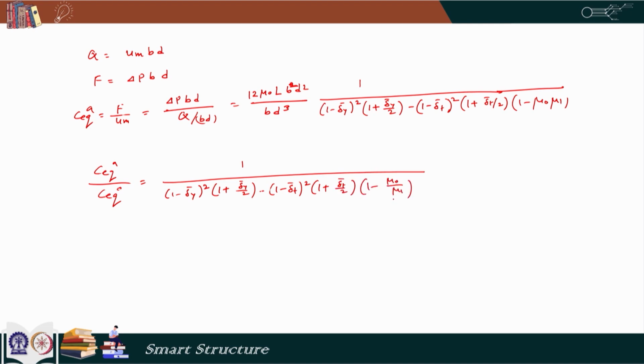So, what we are doing here is to find out the inactive damping, we are just setting these terms delta y bar and delta t bar to 0, because when the fluid is not active at that time we do not have the concept of yielding. So, the constitutive relation is just that of the Newtonian fluid. That means that region does not get divided into plug, or the regions 3 and 4 do not come into picture, all these divisions do not come.